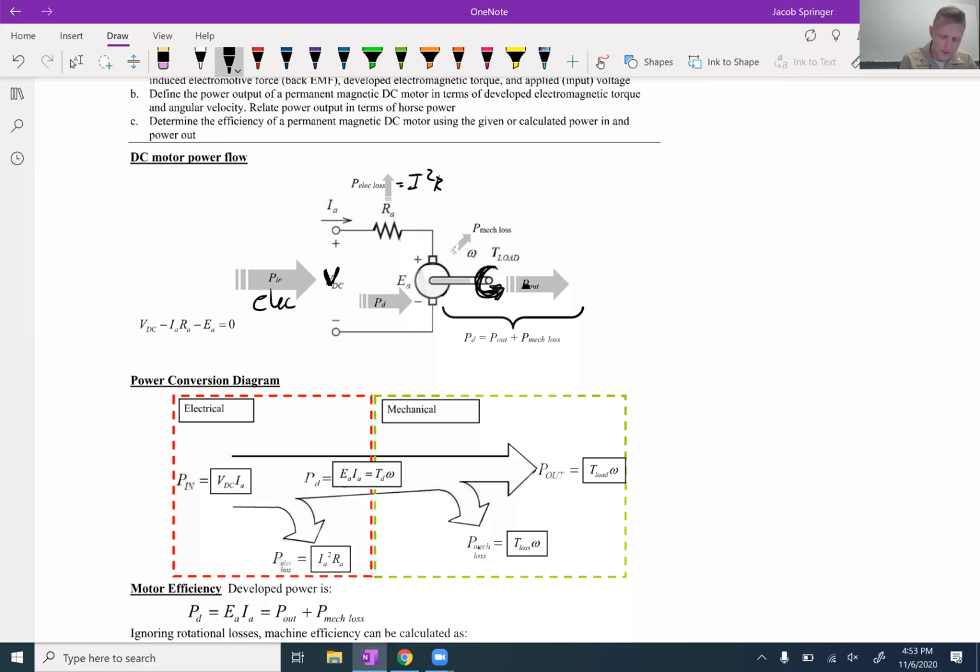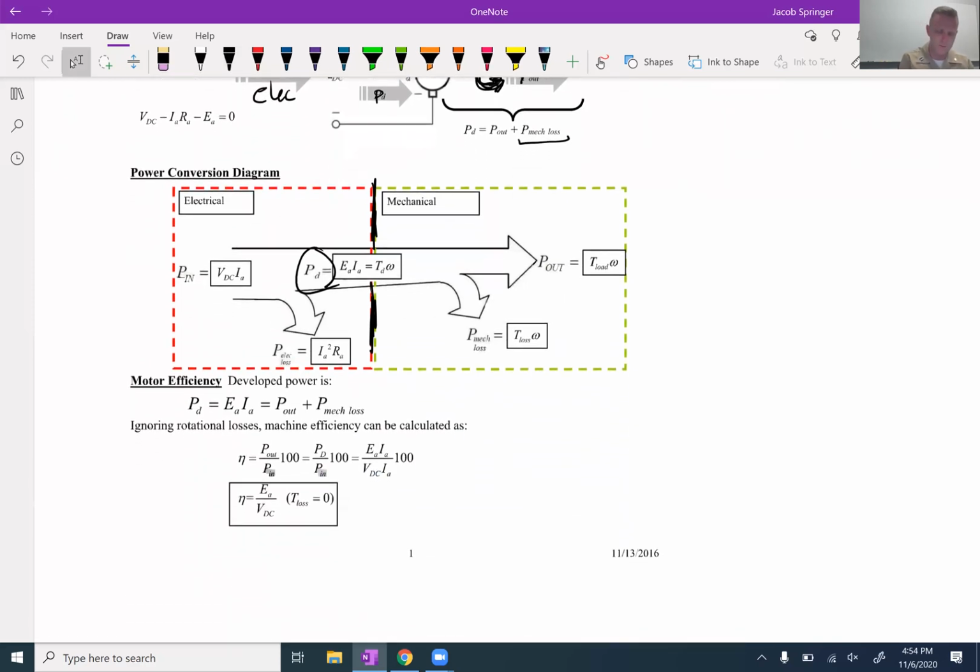And it's telling us that this whole thing has a P out that is going toward my drill, if you will, but then there's friction along the way inside of the motor. And so this force is being developed inside from the electrical to the mechanical. That right there is where the power is developed from the Lorentz force. So there's these equations. And then we have an input power and an output power, and those can be related with efficiency, right? Efficiency is P out over P in.